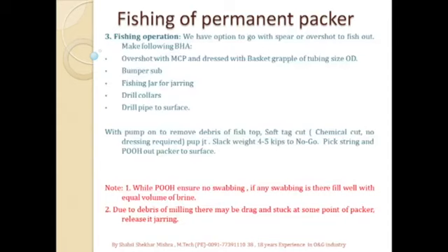Now after the milling operation, if we have to pull out the packer to the surface, then we have to go for a fishing operation. That can be achieved with a spear or overshot.